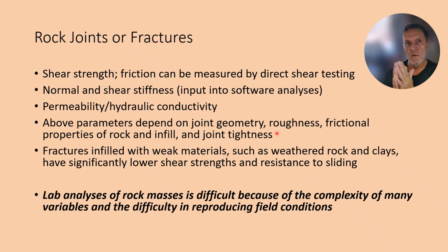If you have a rough joint, it is less likely to slip or fail. If you have infill, like clay filling the fractures, that can lead to instability situations and even failure of blocks along these infills of clay. As you see here, fractures infilled with weak materials, you have lower shear strengths and lower resistance to sliding.